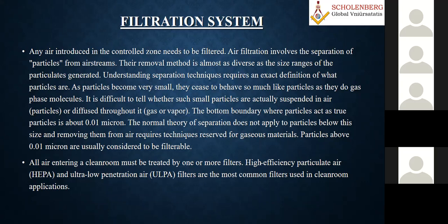Now, having said that, when it comes to the filtration system, all the air entering into the clean room must be treated by one or more filters: pre-filters, fine filters, and then final stages, HEPA filters and ULPA filters. These are some of the most common filters used in the clean room.